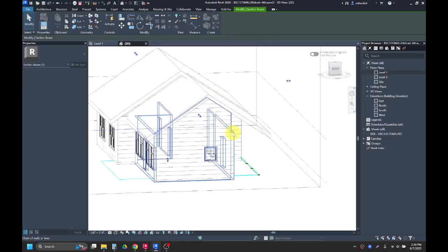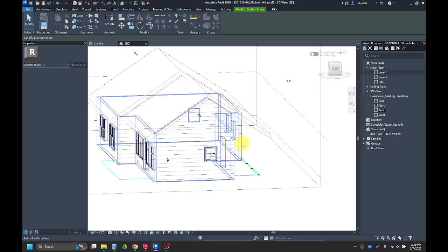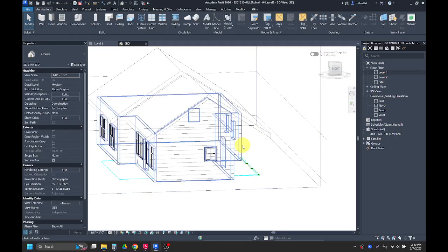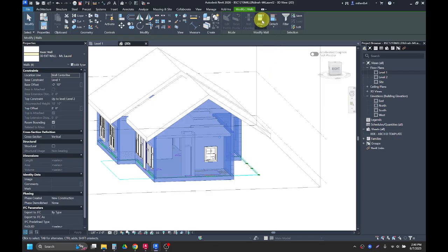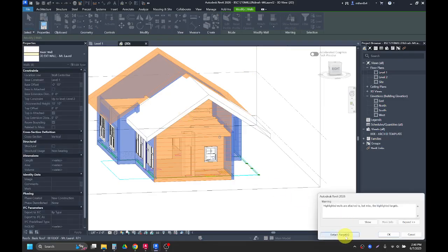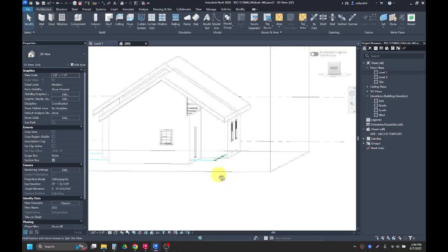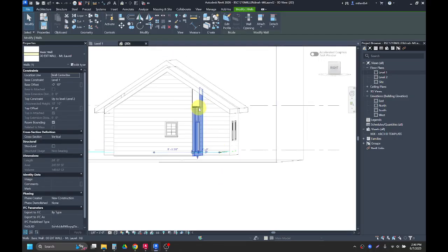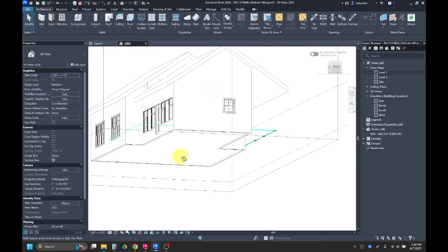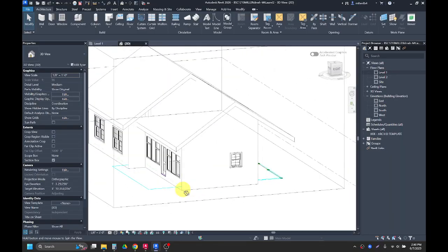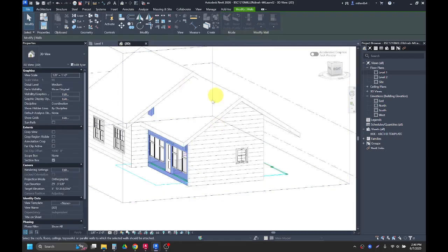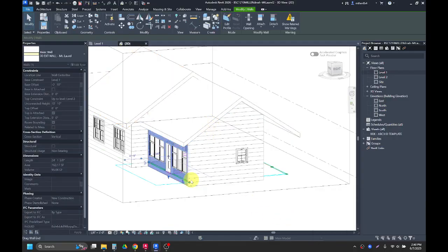And I can even hover and do all of my exterior walls at once by hovering over one, tapping the tab key, and then clicking attach, attach top. Well, actually, since I have 2 different roofs, I can't really do that. But I can get a bunch of them that way. I could click on this wall, attach, attach top, click on this roof. Since I've got different roofs, I've got to do different attachments. This wall, attach top to this roof, and then detach that target.